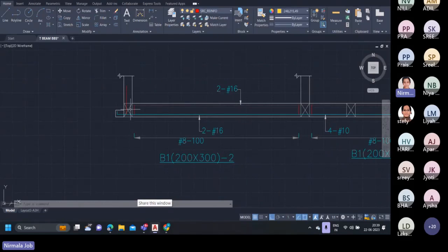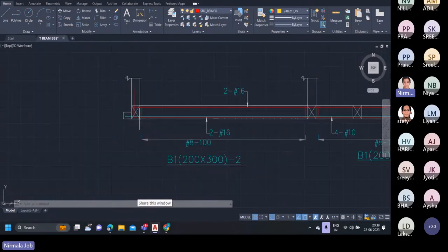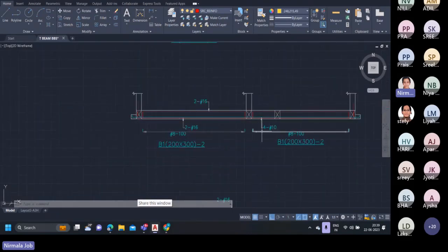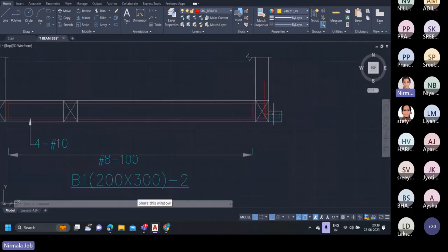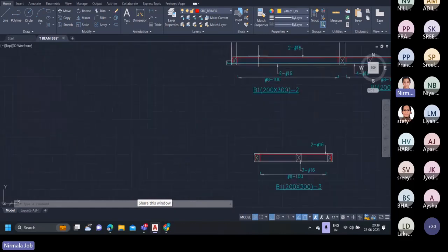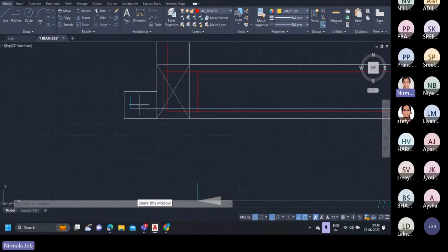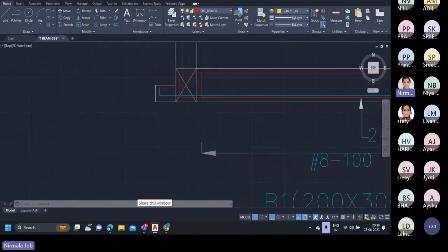And once the beam area is completed, we should draw the T-beam portion over which the beam progresses, and the T-beam should be represented using a projection if it is projecting out from the beam, and the rebars can be distinguished from the remaining rebars using another color, but the layer should be the same as that of the rebar, that is SRC reinforced.